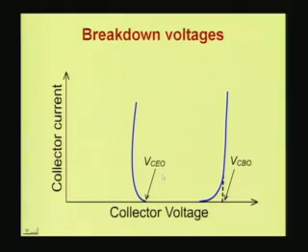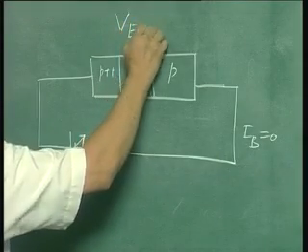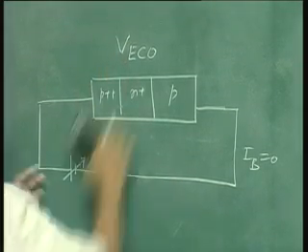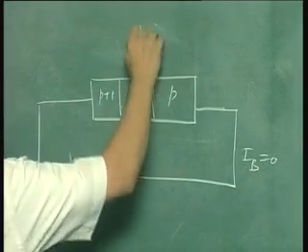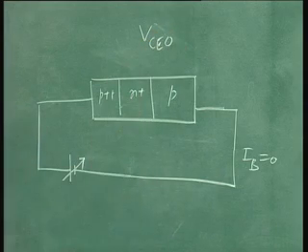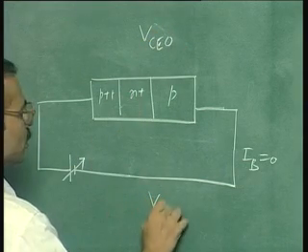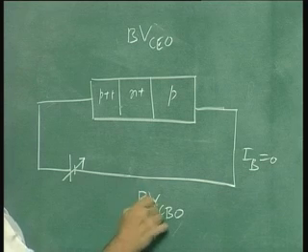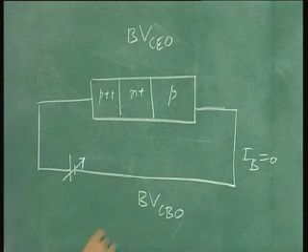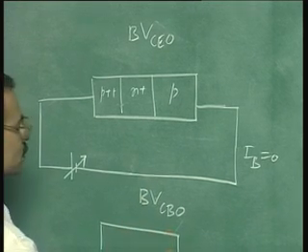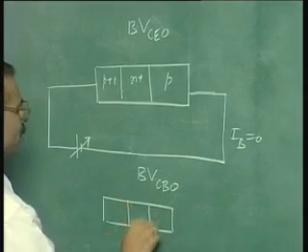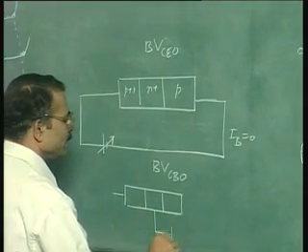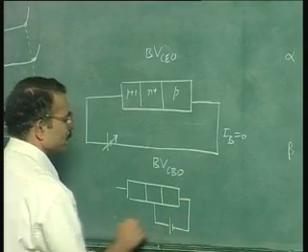So this is for Vceo. For Vcbo, when you are talking of breakdown, you normally use the B here. BV stands for breakdown. For BVCBO, the condition is as follows. You have this transistor, the emitter is open, and you are measuring the breakdown voltage between collector and base.